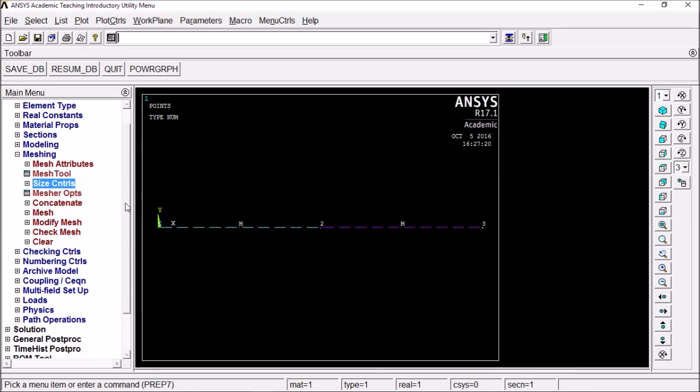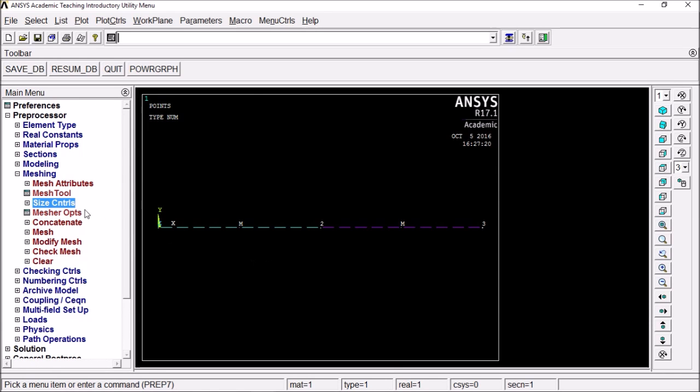So that's as simple as it gets for meshing lines. Just a reminder again, when you do sections, you're going to specify divisions in the y and z direction, and that combined with this x direction will create the grid that is your finite element mesh when you go to mesh. So that's it for meshing lines and areas.